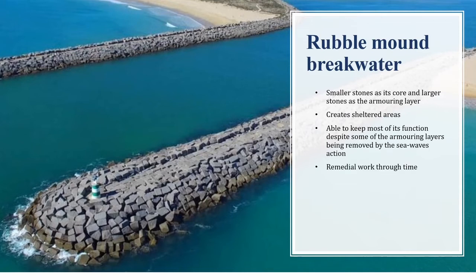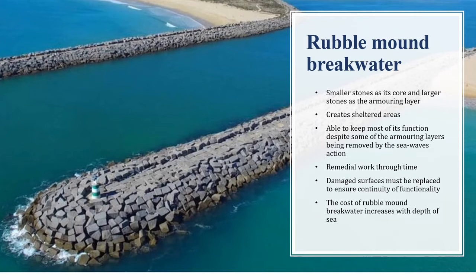However, remedial work through time is needed to fill the voids, and additional stones must be provided to replace lost layers or damaged surfaces to ensure continuity of functionality. The cost of a rubble mound breakwater increases with the depth of the sea.